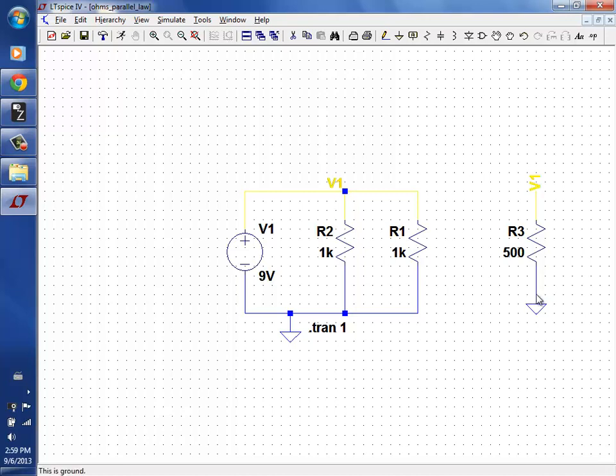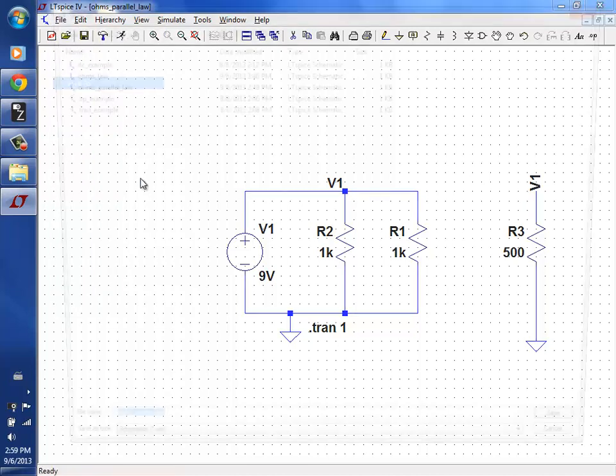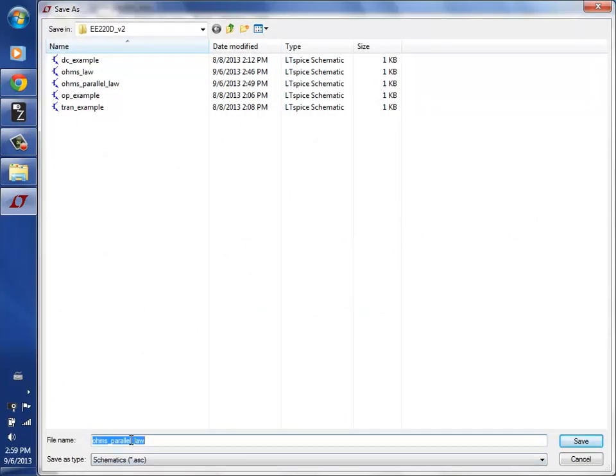Right click, highlight net. If I grab the stretchy hand, the pulley hand here, and I ask you now, trick question, see if you're paying attention, how much current flows down here to ground? None. Where does the current through this resistor flow? Flows like this, back over here, but you don't see the wire even though they're connected. So what's going to happen to the current in the voltage source now? It was 18. What's it going to become? 36.